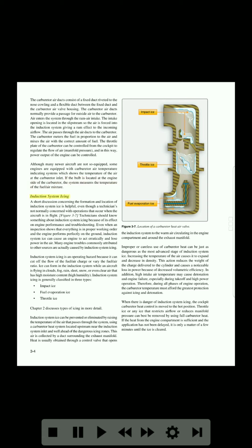Induction system icing. A short discussion concerning the formation and location of induction system ice is helpful, even though a technician is not normally concerned with operations that occur when the aircraft is in flight. Technicians should know something about induction system icing because of its effect on engine performance and troubleshooting. Even when an inspection shows that everything is in proper working order and the engine performs perfectly on the ground, induction system ice can cause an engine to act erratically and lose power in the air. Many engine troubles commonly attributed to other sources are actually caused by induction system icing.